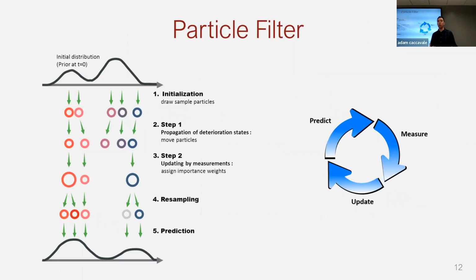So the core of how the robot is going to be updating its map is using a framework called a particle filter. This is going to get a little abstract if you're not familiar with Bayesian filtering, but at a high level, this is going to follow that same pattern where the robot is going to make a prediction, compare that to its measurement, and then update its belief based on that. So in a particle filter, generally you're trying to estimate a probability distribution. And the way you're doing that is with a set of particles. Each one you propagate with the dynamics, you adjust their likelihood based on how well these match your measurements, and then you resample keeping the likeliest particles.